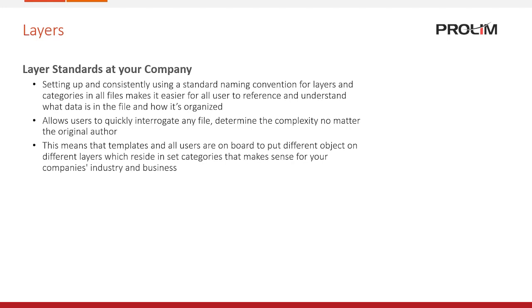So understanding the standards at your company provides a way for you to maintain consistency across your users. Having those standards, you know that at your company, everyone should be putting your solids on layer 1. So you know layer 1 will have all those solids on it. You don't have to go digging, turning on all your layers to find all the solids and verify that they're all on the correct layer. So those provide that consistency. And you can customize all of this within your template files.